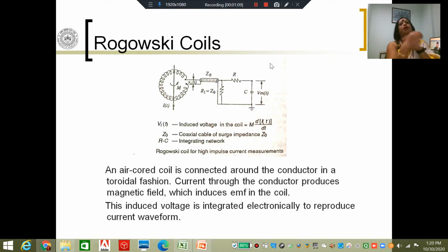And the magnitude of PD is not really a very meaningful quantity unless we know from which location the PD is traveling to the sensor, because as the PD travels over a large distance and through different complex equipment or components, there will be considerable attenuation. And so a small magnitude may not necessarily mean a small PD. It depends upon the location.